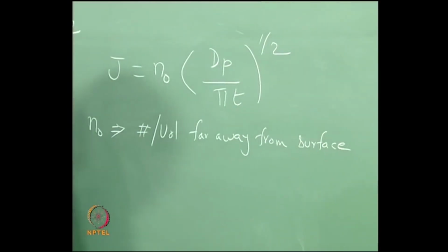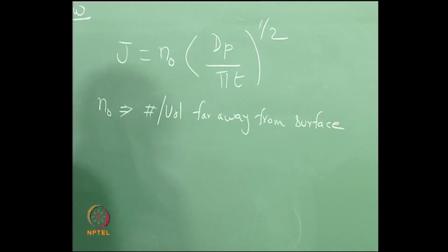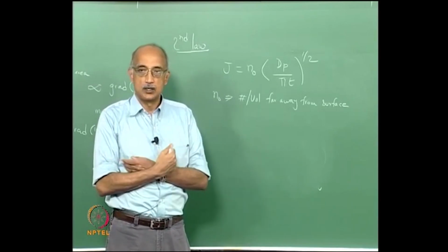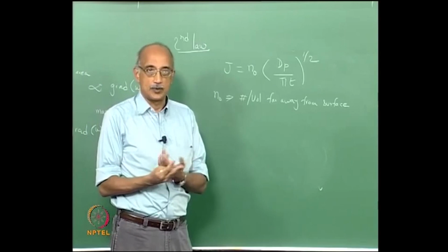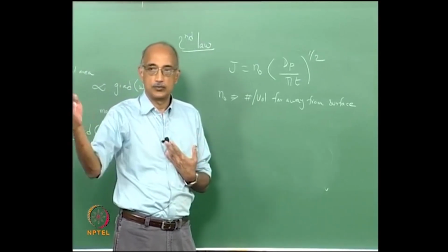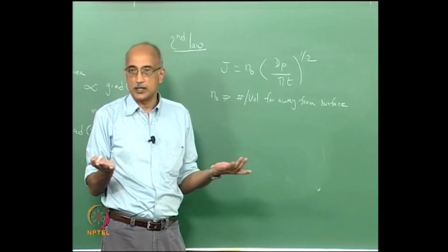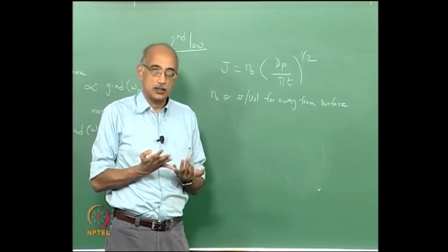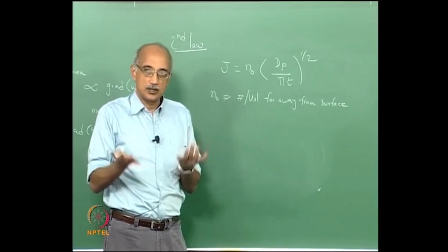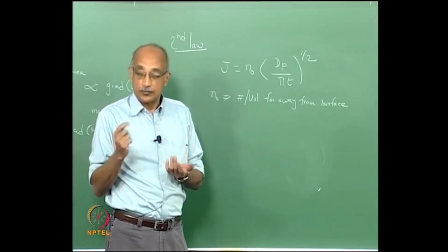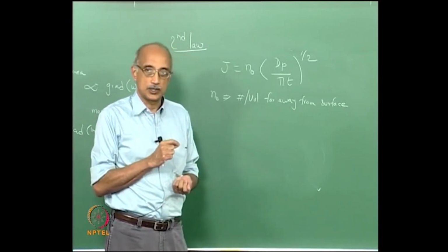By the way, one of the things you have to consider is why does flux even happen? Why does mass diffuse in a certain direction? It is because you establish a gradient in that direction, right. But how does the gradient get established? If you have a free flowing fluid and you are assuming that particle movement is completely random, then in theory there should not be a gradient, right. Essentially the concentration should be roughly uniform everywhere if concentration distribution is occurring only through diffusion processes.